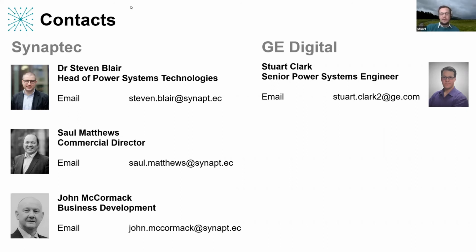But you can read more about that kind of topic in, I think it's the most recent 2018 Cigre paper we published, which talks about data streaming there. Latency is, for monitoring, generally manageable. It's not unusual for a monitoring system to have latencies, say, in the 5 to 10 second region. It's not that your control room application will be waiting impatiently for data to arrive within 100 milliseconds.